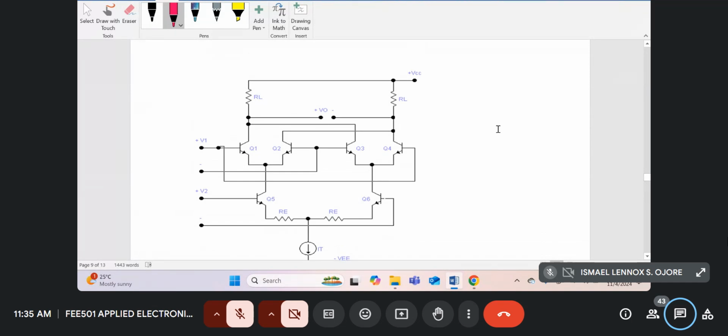So this is called the Gilbert's multiplier cell. This is the part of the circuit that performs the multiplication. Q1 and Q2 form a difference amplifier. Q3 and Q4 form a difference amplifier. Their outputs are connected in parallel, but in a very special way. And then to vary the transconductance, we have the other difference amplifier comprising Q5 and Q6.